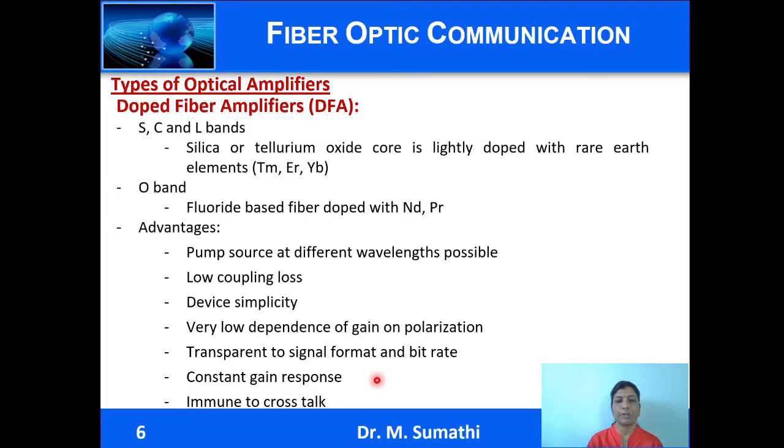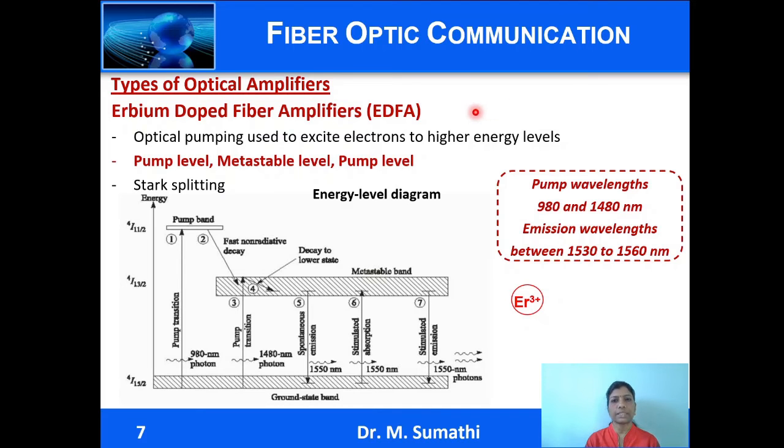And the gain response can be made constant by using gain flattening filters, and it is immune to crosstalk. So we shall discuss erbium doped fiber amplifiers or EDFAs, which are very popularly used in the C band and which was responsible for WDM systems to become popular.